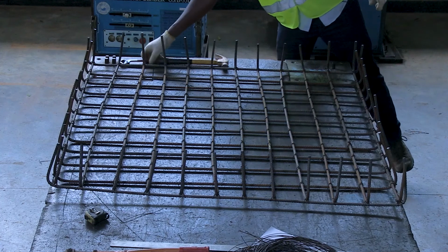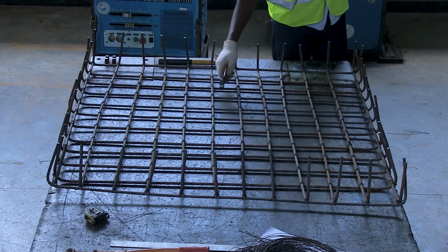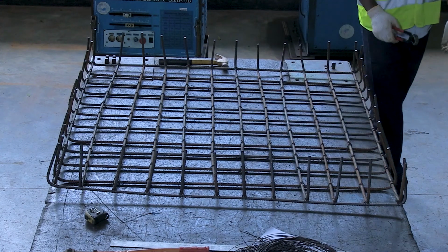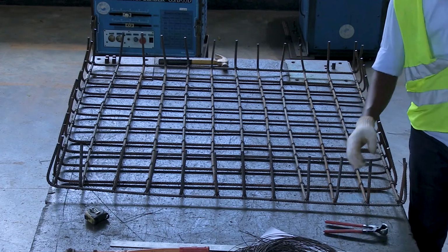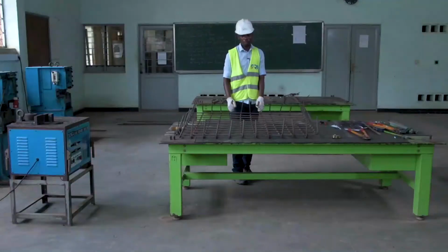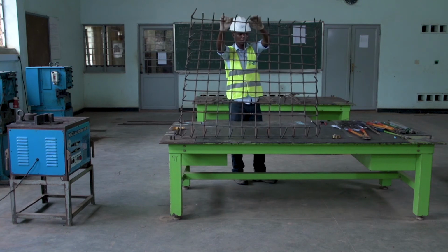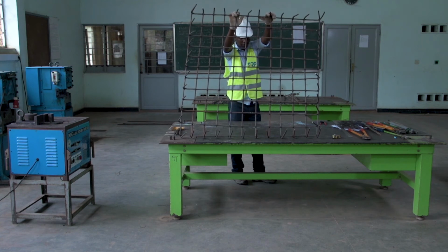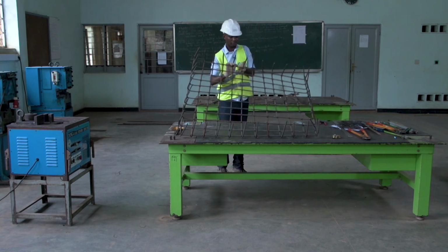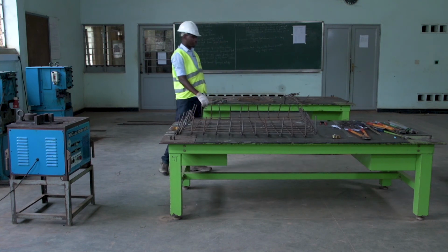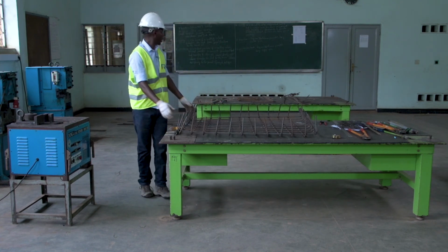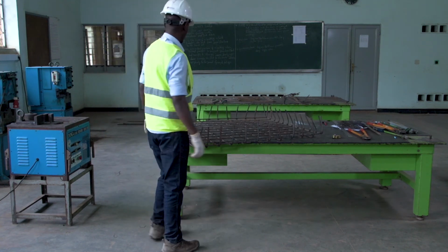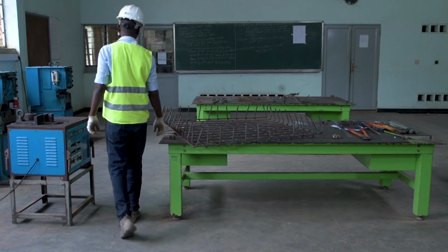Then the main bar is this one, the down one, and the distribution bar is the top one. So this is our finished product we call a square footing. This one with 150 over 150. It is a square footing. So after, remember, our task is to perform a footing with subcolumn framework. Now let us start to make our subcolumns.